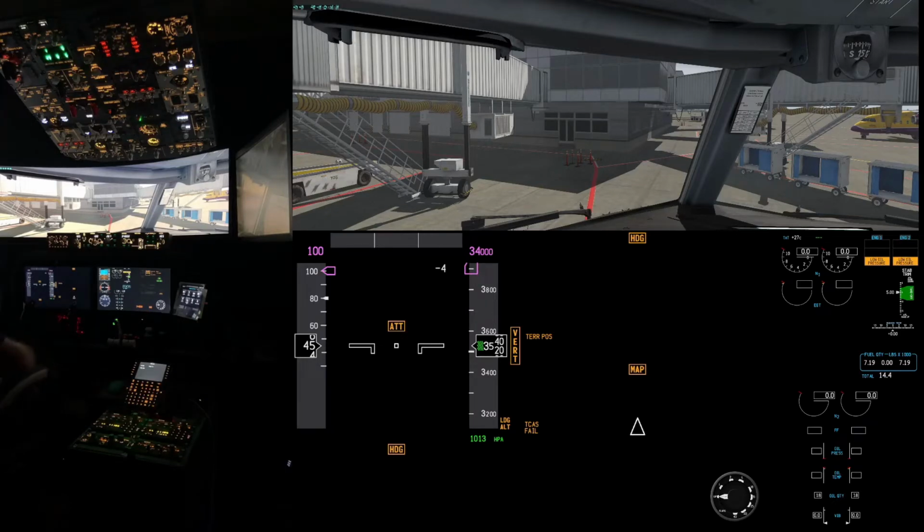So now what I'm going to do, I'm going to start to turn some other parts of the plane systems on, and we're going to start in the overhead panel in the top left hand corner. And typically the flow that you do when you're working on the overhead panel is starting in the top left, going down to the bottom across each one of the different towers of instruments. So starting with the left hand side, we are going to turn the yaw damper on.